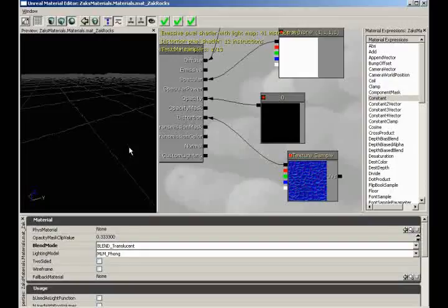Technically, what's happening is the material is reading the pixels that are behind the surface. It is pasting those onto the surface, and then it's pushing them around a little bit. And how does it go about pushing those around? Well, it actually does it in 3D space. Or I think technically it's 2D, but it uses color information. It's going to use red values to move along the x-axis and green values to move along the y-axis. So it's just taking those pixels and perturbing them, giving you the simulation that you have refraction.